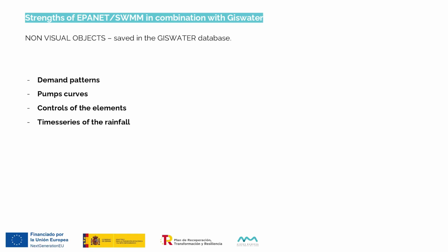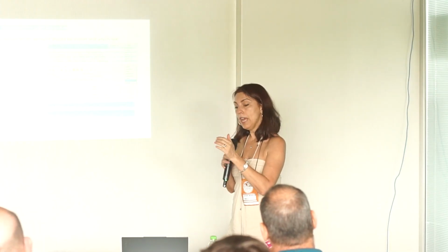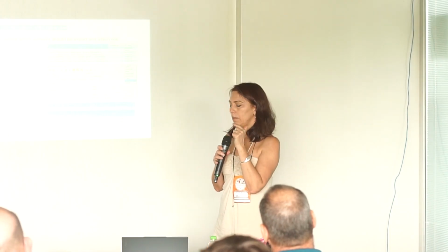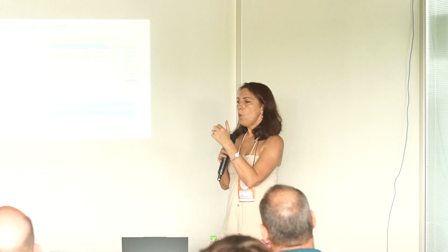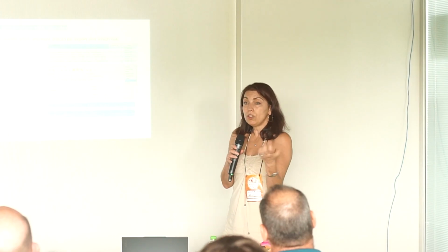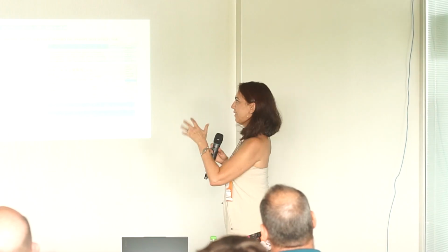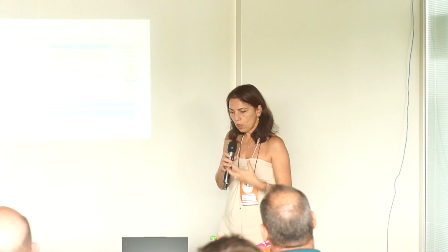Here is the capture of the table where you define what a sector is, saying the name, the head of the zone, the two arcs, and you can even say, besides the valves that are closed, which other node you want to consider as a stopper, or if you want to consider something as closed but ignore it. So it gives you this option.